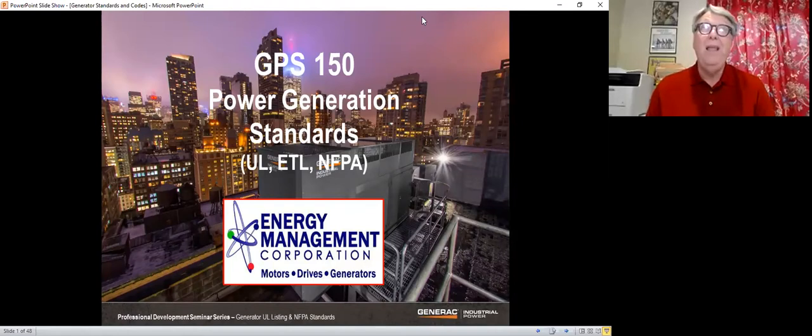Now, an emergency generator, according to the EPA, is a totally different thing than an emergency generator for the National Electrical Code. The EPA just says an emergency generator is one that's there to back up a utility. So they do that, I think, to make sure that we're properly confused by labeling things the same that are not the same. But we're talking about the National Electrical Code. That is NEC Section 700. NEC Section 701 are legally required generators.